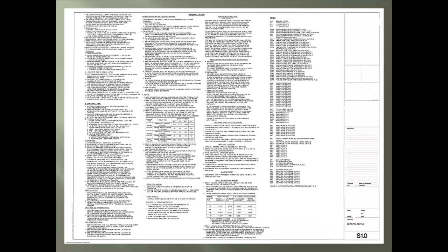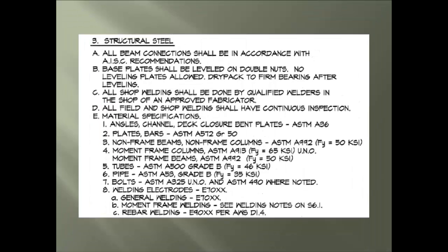The last but most important item on the general note sheet is the information for each structural category. Now, if you are looking for an architectural item, you would have to search the general note sheet found in the architectural drawings. But in this seminar, the topic is steel, and we will look closer at that specific topic. We see here on the left side column that number 3 covers the steel. So, we see how information specifically for steel is given.